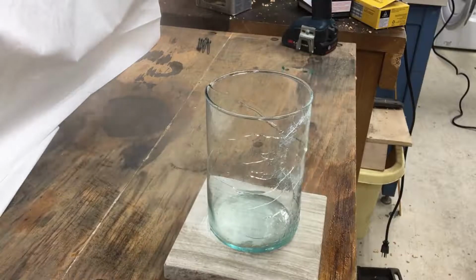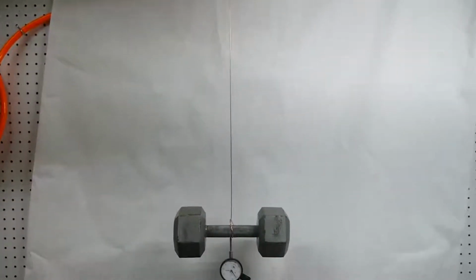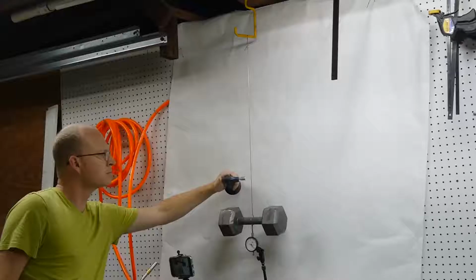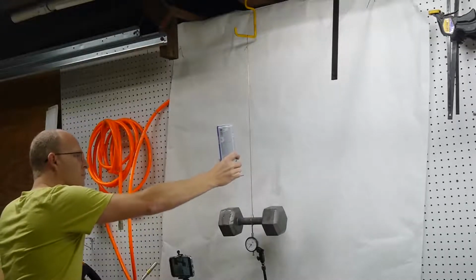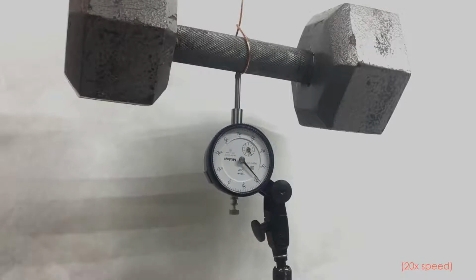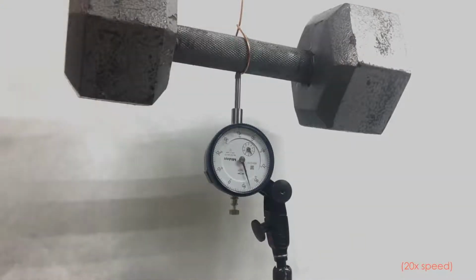Thermal movement is something that has to be considered in nearly every field of engineering, because there aren't many places that don't see fluctuations in temperature. And there are really only two options for designing to account for thermal movement. The first one is to prevent movement by constraining it, a feat that is almost always impractical. Thermal movement can generate tremendous amounts of internal stress. Watch how this wire can lift up a weight just by heating it up and cooling it down.